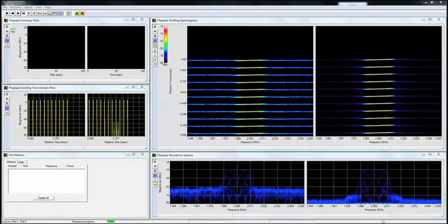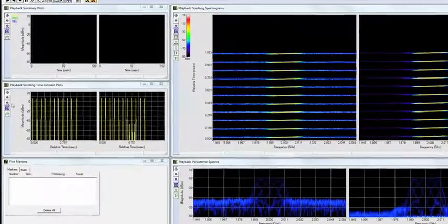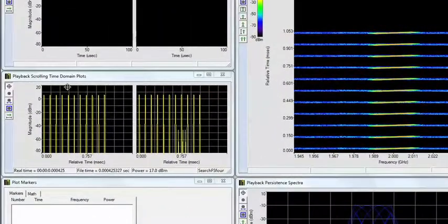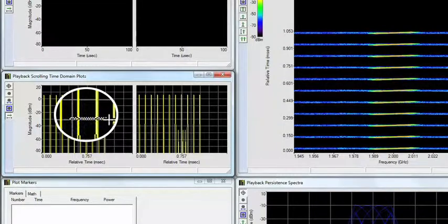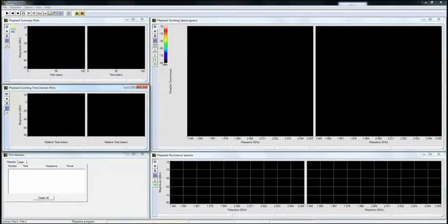So one way to zoom in and see if visually we can at least begin to identify whether there's a time difference, how significant it might be, and whether it's worth measuring or not, is, since we're doing time domain measurements, to use the scrolling time domain plots and designate, instead of spanning a period of time that includes multiple chirps and therefore compressing visually what's going on, let's just select 2 chirps, which show up as pulses in the time domain, and tell Spectro-X just to play those 2.